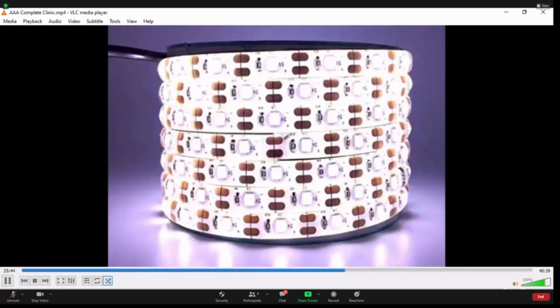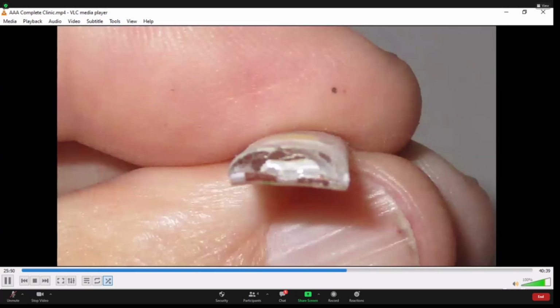The front of the unit is curved and tends to roll when soldering, so I place the unit curved side down and place a piece of masking tape on it to hold it steady. With the back side up, I pull back a bit of the backing tape. The front of the LED indicated which of the soldered pads was for the ground and which was for power.